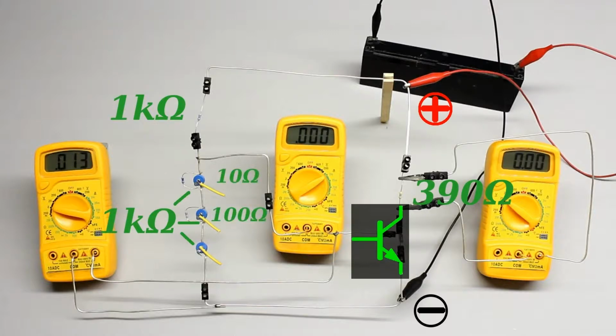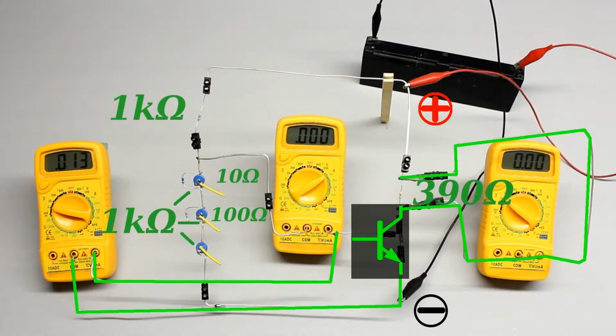A resistor of 10, respectively 100 ohm is soldered in parallel to the 2 upper potentiometers. The bottom potentiometer is used for the rough adjustment and the 2 upper potentiometers facilitate a fine-tuning of the voltage divider. 1 voltmeter is used to measure the voltage drop between ground and base pin. The other one detects the voltage drop at the resistor between the collector pin and the positive terminal, which is called load resistor. It detects the current running through the base pin.